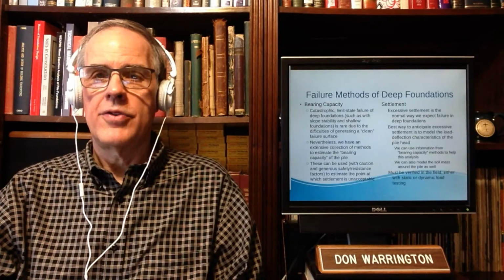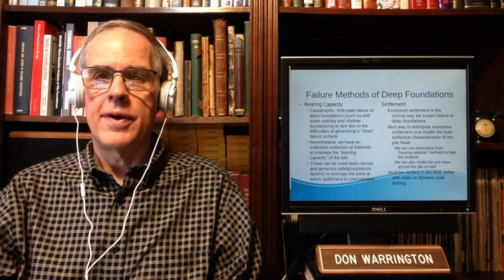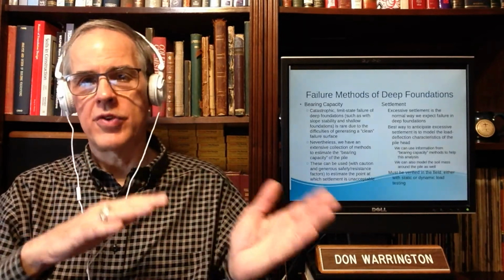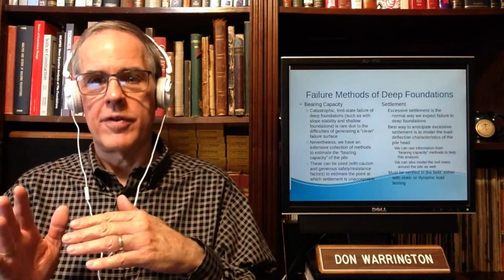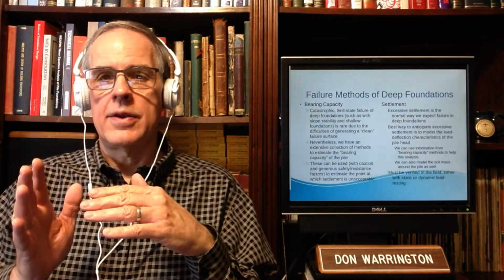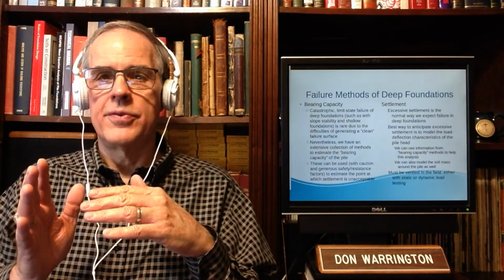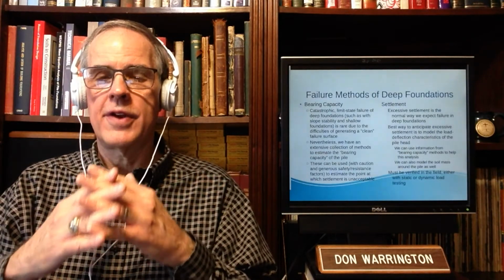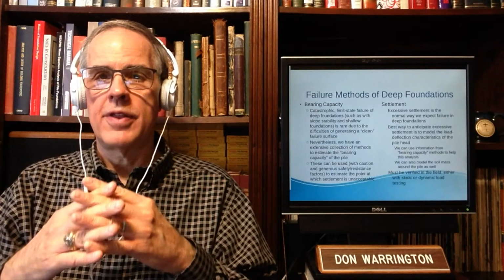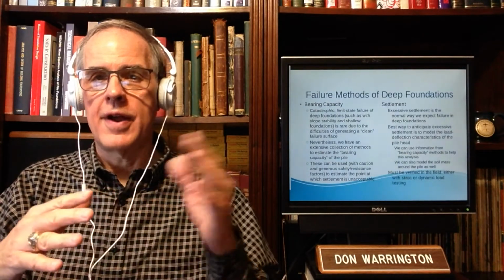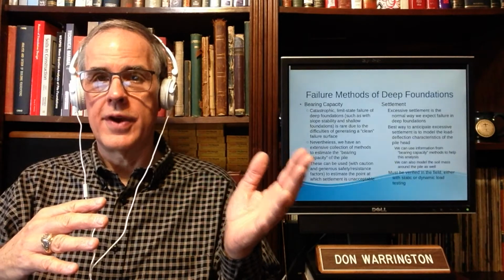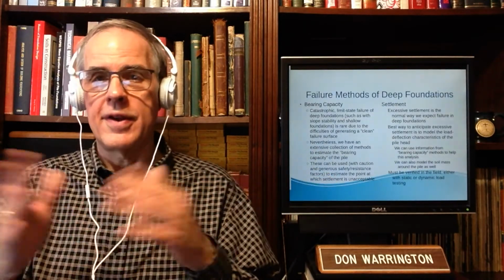The methodology we have is based upon something I discussed earlier, which is we design for strength and we design for service. And with driven piles, really the two run together. But because of our design methodology, we have set things up so that they are basically designed separately.